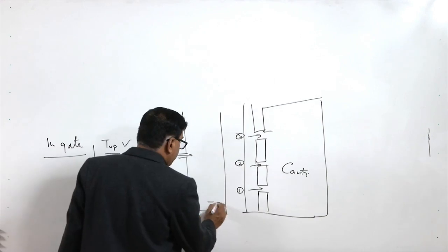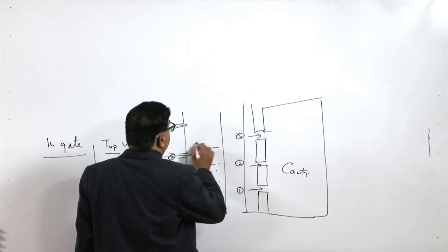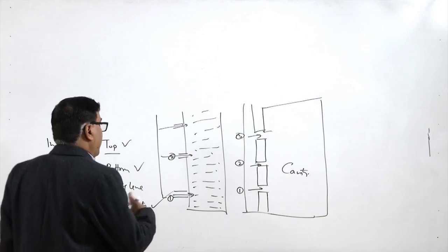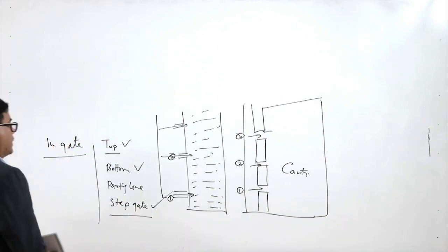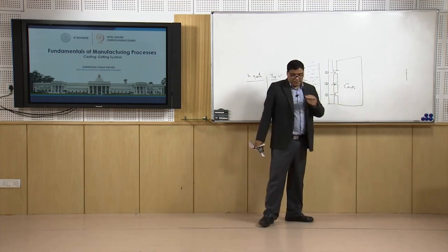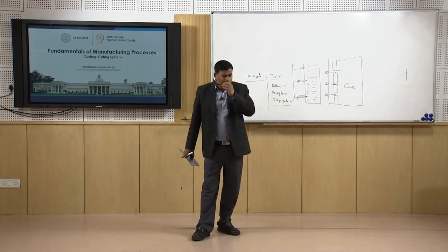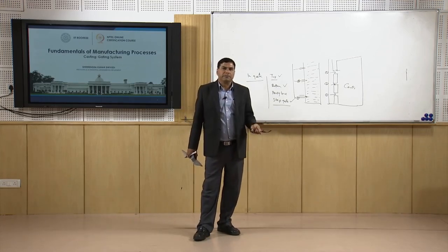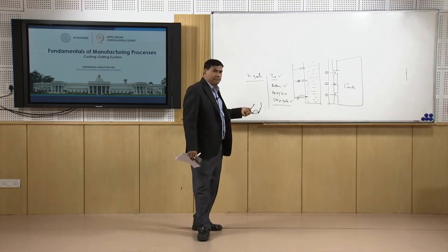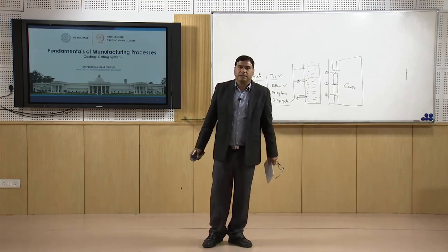Here the feeding starts from the bottom, and then gradually it is filled up to the top in order to facilitate the directional solidification and have the suitable temperature gradient. So, the purpose of having a number of gates is to fill large size cavities in the minimum possible time, while having the favorable temperature gradient.